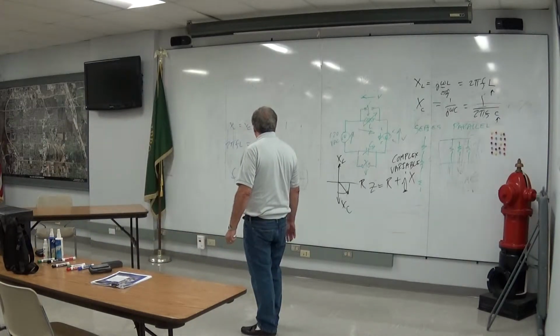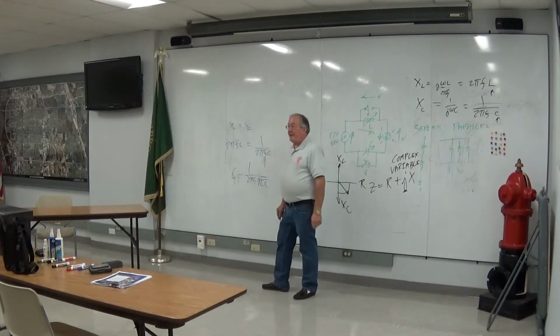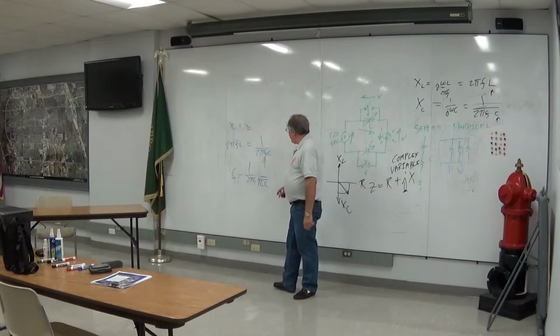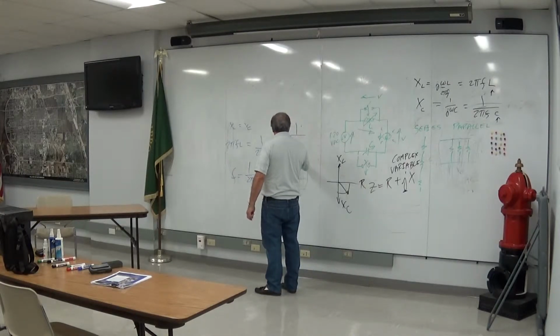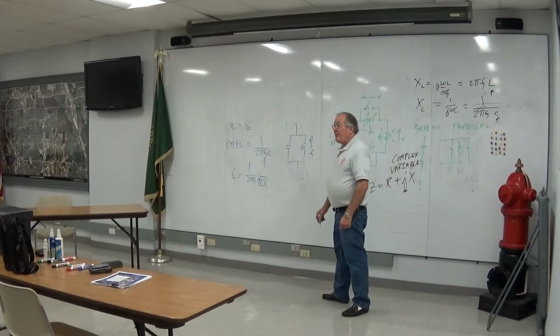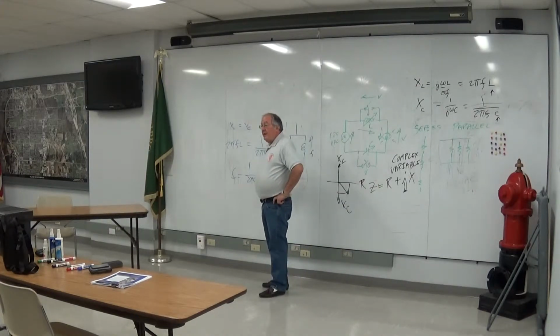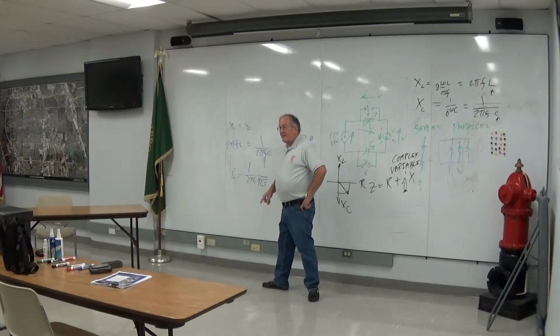What's the practical application of that? All right, the practical application is to say, I want to know what frequency I'm going to get if I pick a particular capacitor and a particular inductor. Exactly where am I going to get that voltage? What frequency am I going to be at when that voltage shows up? And that's how you compute it. What's interesting is, this guy's in the denominator, so if L gets bigger, the frequency of resonance goes down. If the capacitor gets bigger, the frequency of resonance goes down.